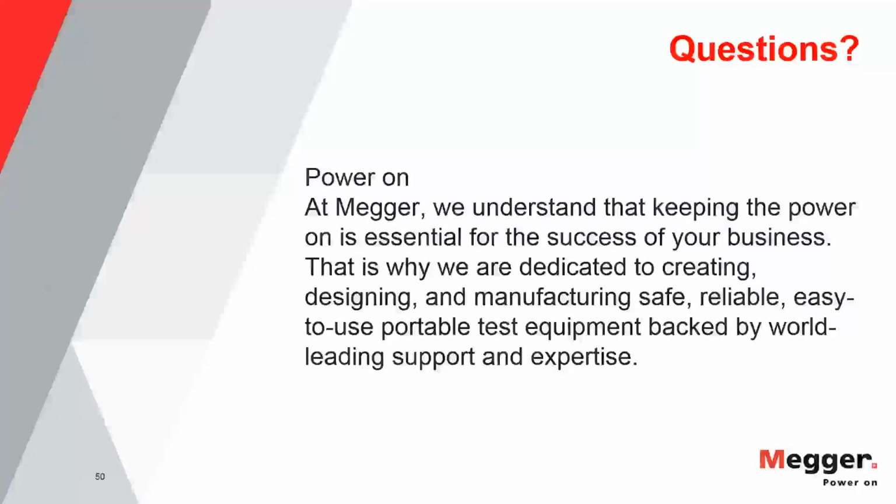For the test capacity on VLF, are you just talking about PD testing? No, I'm not. It's testing cables in general. The cable's a big capacitor, so we have to be able to fill that capacitor up and discharge it in the time that we have per cycle. So VLF withstand testing especially does suffer from this maximum capacity of the cable as well. So when we talk about the cosine rectangular, the damped AC, we have a much higher testable capacity, even on just the basic withstand testing.